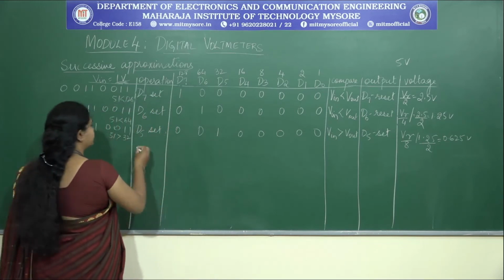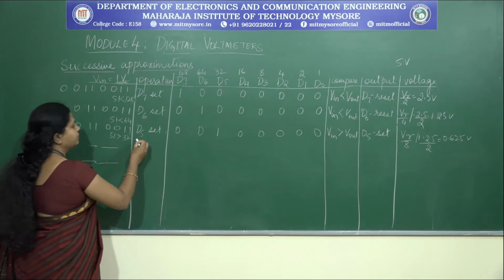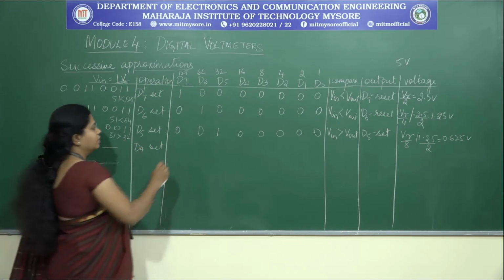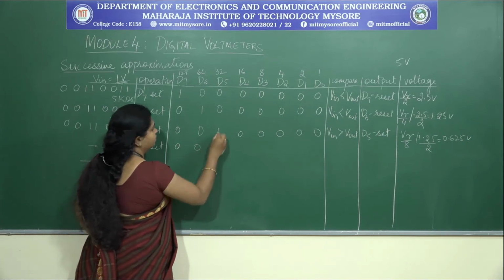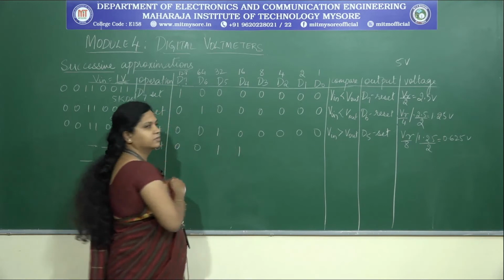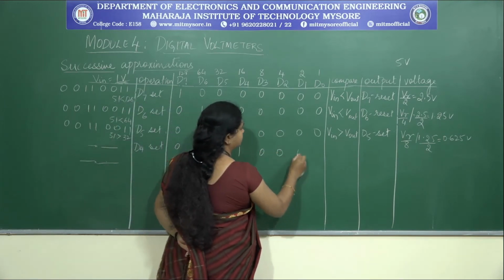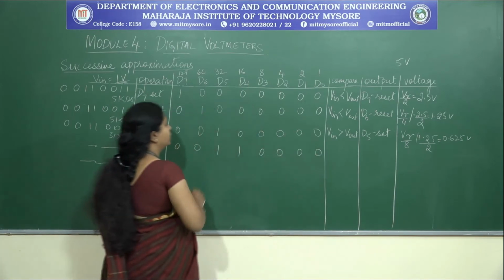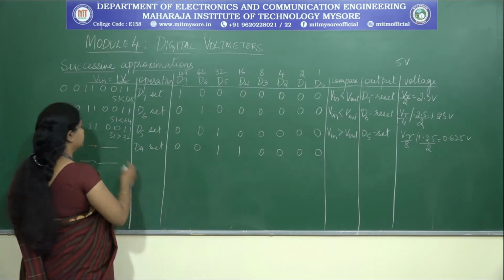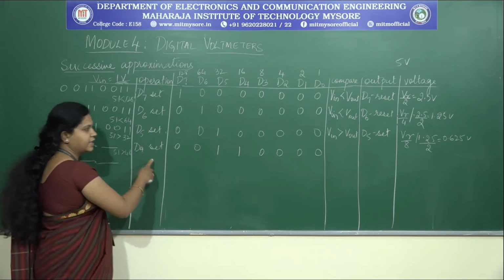But for the next clock pulse what should you do? This will continue for the number of bits. Now here you should set D4. So 0, 0, D5 should be as it is, whereas D4, take it like this, 0, 0, 0, 0. What is the value? 32 plus 16, you will get 48. So 51 is greater than 48 in this cycle.